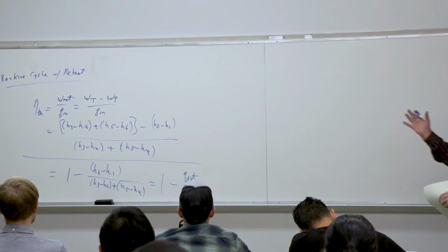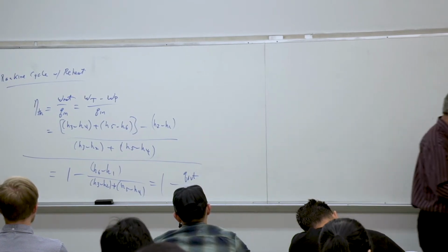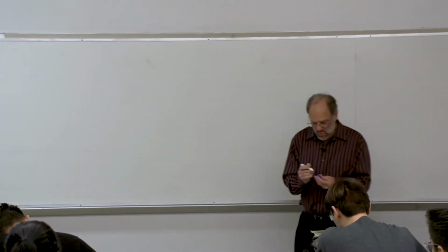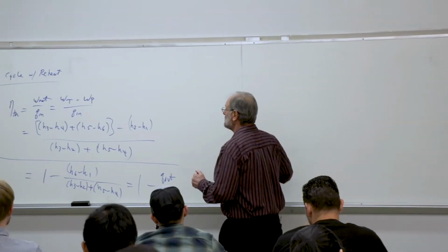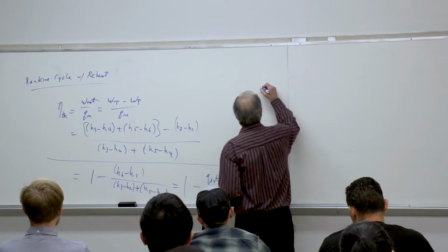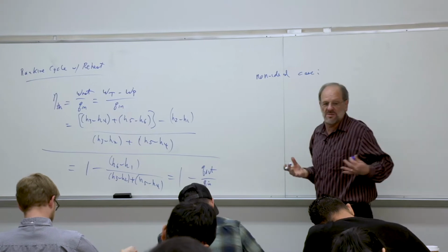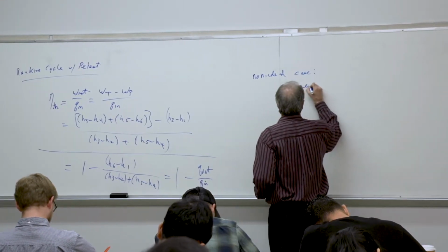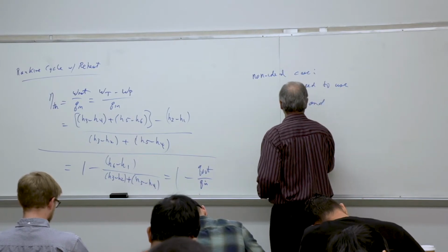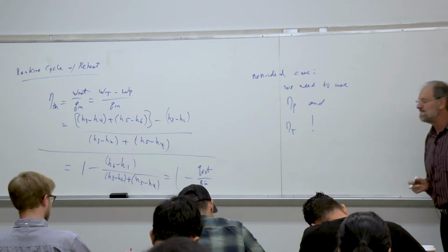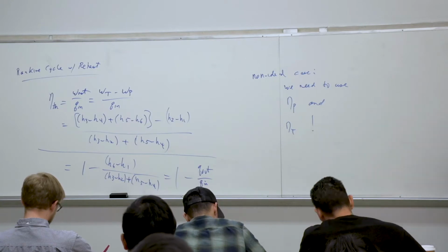Okay. So nonetheless, we could use either this equation or this equation. It's going to give you exactly the same results. Okay, now what if we have the non-ideal case? I mean, basically, as this was set up, this was for the ideal Rankine cycle with reheat. If we have the non-ideal case, then like we've seen before, this basically just means that we need to use the isentropic efficiency of the pump and the isentropic efficiency of the turbine, right? In that case, we would have the same methodology as we would have covered previously.